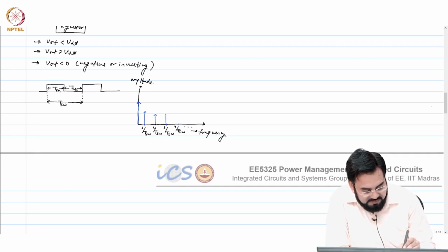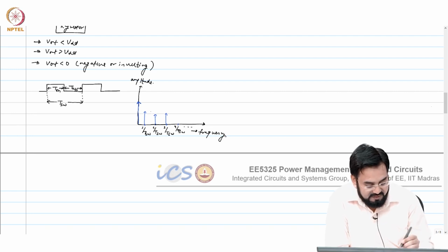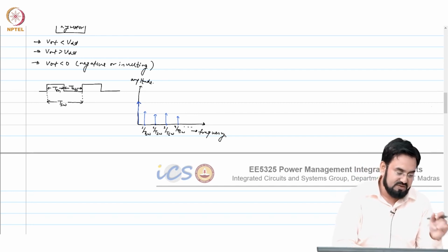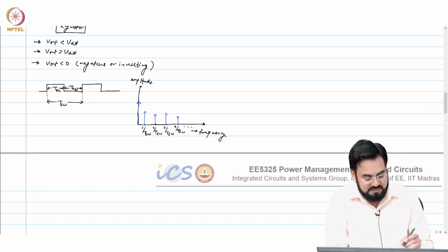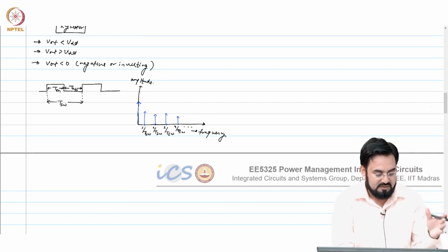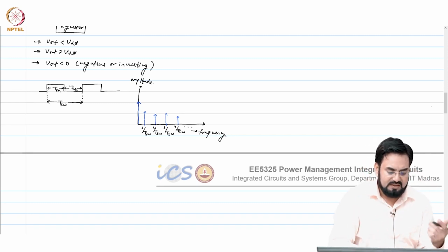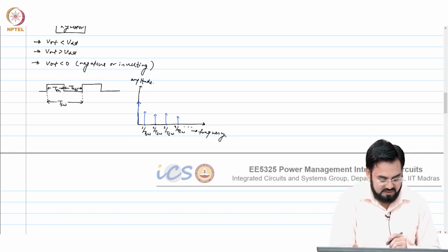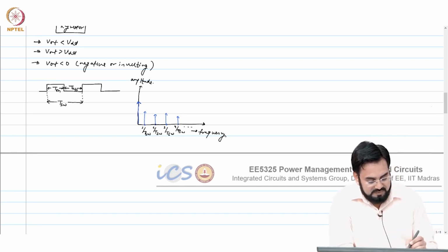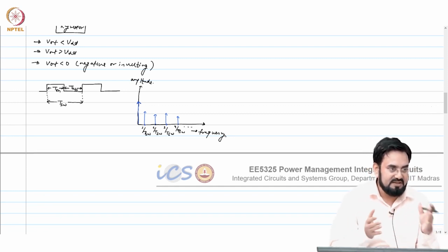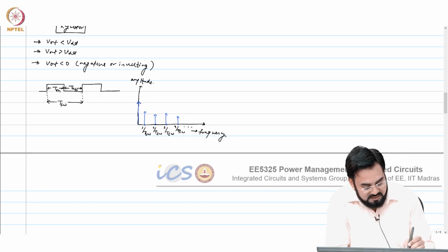In fact, some of them might be more than the others. If you look at the even harmonics, it's not necessary that it will keep decreasing, but it depends on your duty cycle actually. So the expression is not straightforward here when you take the Fourier transform, or the Fourier series, of a triangular signal or any other. And if it's a perfect square wave, then it will have only odd components, but if its duty cycle is not uniform, then it will have both odd and even.